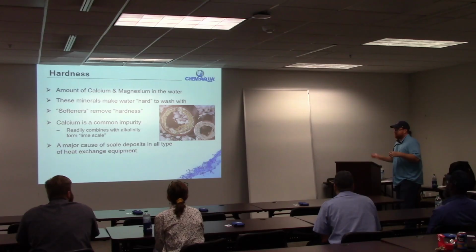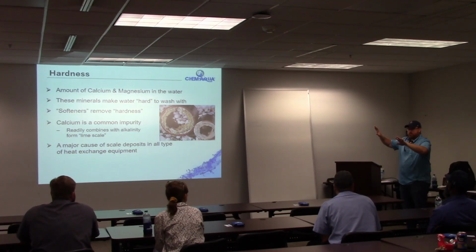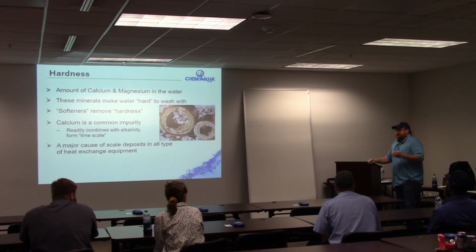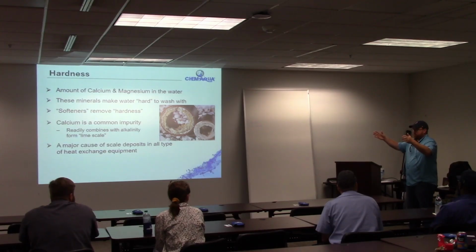I'm sure y'all have seen cooling tower fill where you see calcium buildup on the fill. If that calcium buildup is in an area where there's constant water flow, that's a water treatment issue. If that buildup on the fill is in an area where there's intermittent water flow, that's evaporative deposits. When a cooling tower operates, your fan speed is variable depending on your load, right?